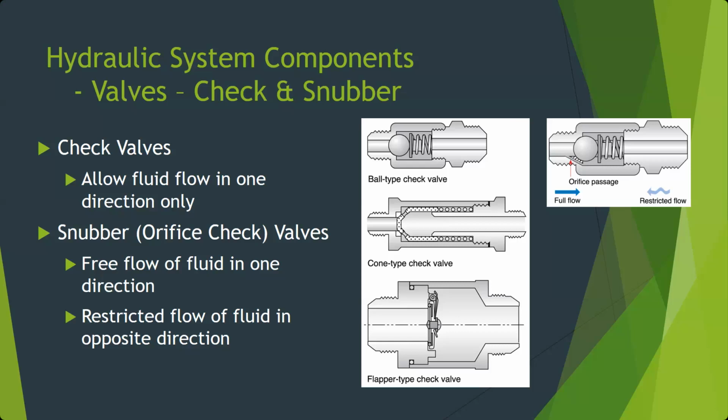So it tends to deal with actuators. The one where these are most common, and it's a landing gear thing, that's why it came up yesterday with the group that was doing the landing gear lab, is when you retract your landing gear, you want all that pressure to pull the gear up. It takes a lot of energy to get that gear to pull up because you're fighting against gravity. When you go to extend your landing gear, you don't want the landing gear to fall, right? You've got all that energy, the gear wants to fall.